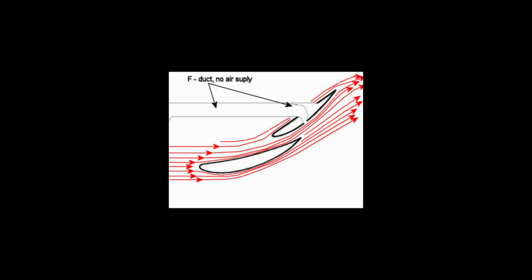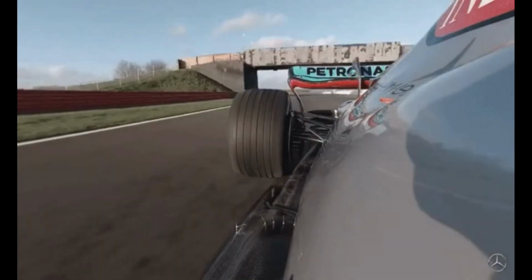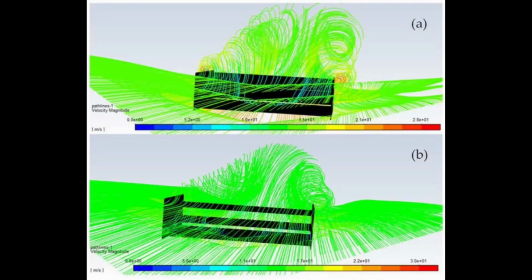It almost resembles an upside down airfoil. Another structure is the drag reduction system, which controls the rear wing's surface area. And according to the force coefficient, as we decrease the reference area, which in this case is the wing's surface area, we get a smaller force, which decreases drag.